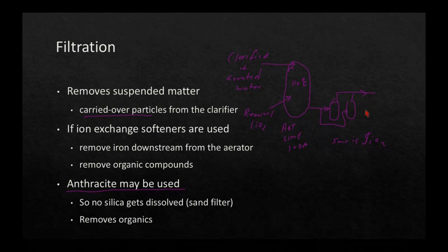So for that reason, we do not use sand filters, because we're going to end up redissolving silica.